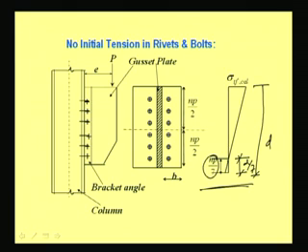With this assumption we first find the possible neutral axis depth. Then we find where the actual neutral axis depth is. Then we can find sigma Tf cal, that is the tensile stress coming in the extreme fiber of the rivet. Those things we can calculate, and then we can see whether it is safe or not, right.